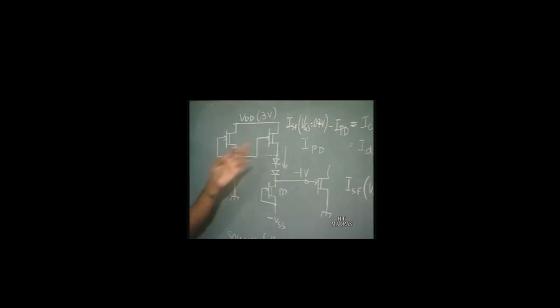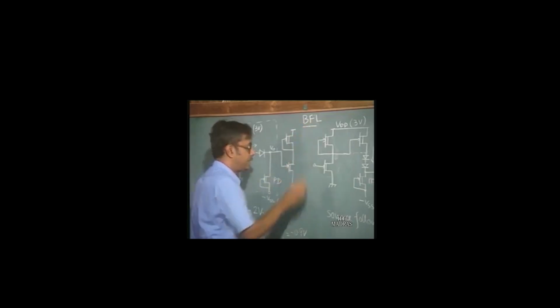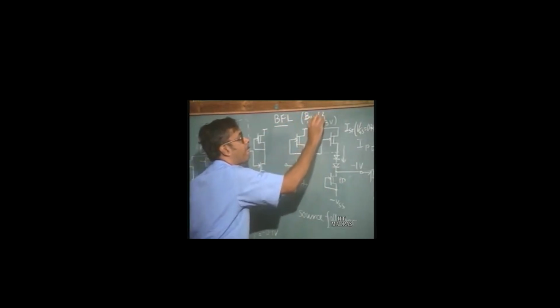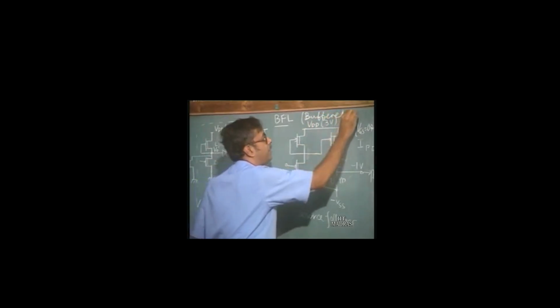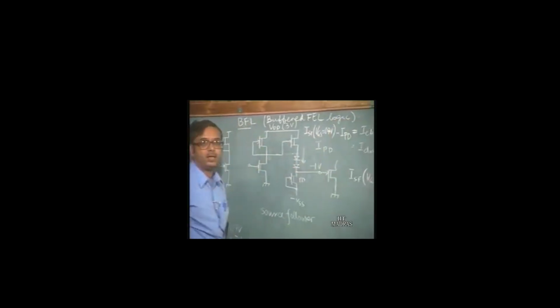It is an improvement on that from the speed point of view, because during the switching period you have larger currents to charge and discharge the output capacitances. So, this particular logic family is called the BFL, which stands for buffered FET logic. BFL, or buffered FET logic.